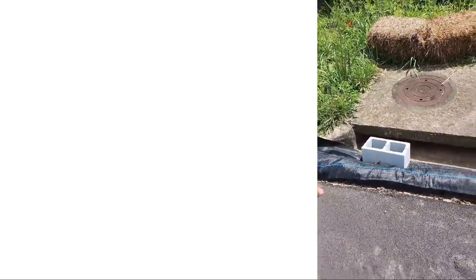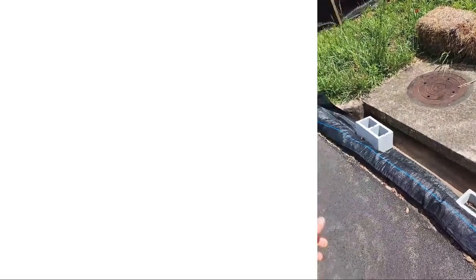This is the stormwater drain right here. So whenever there's a stormwater drain in any of your construction areas, you have to put this thing here. People call it different names, but it's basically something to stop the silt from coming off and going into the storm system, which is not allowed. You can get fined for that. So you definitely got to stay out of the storm drain area. So this is all part of our erosion control.